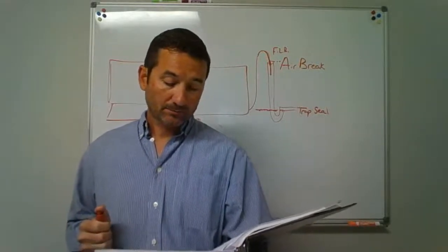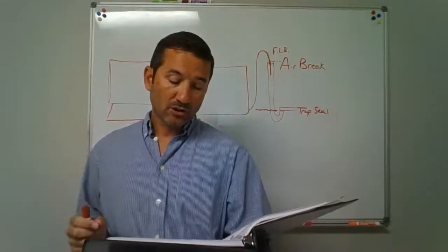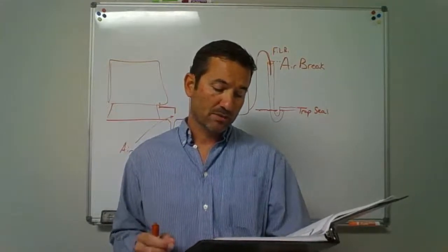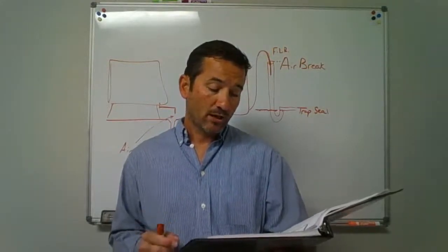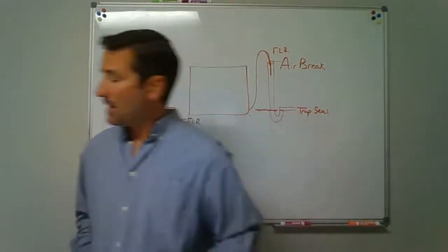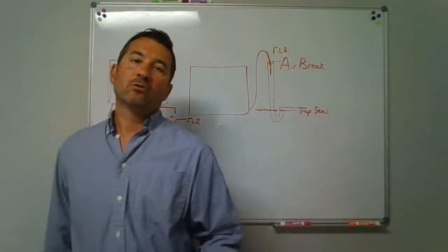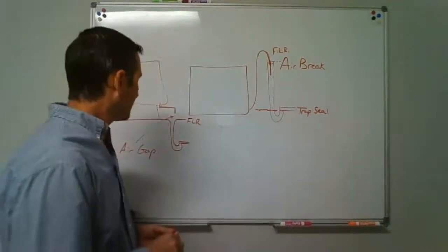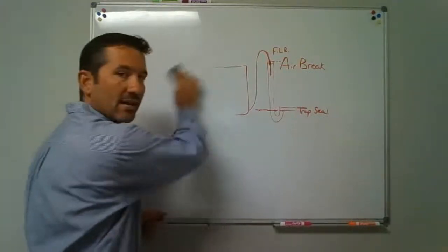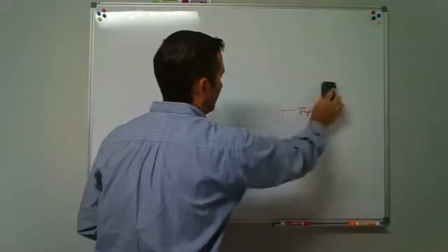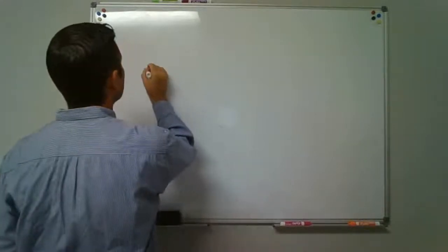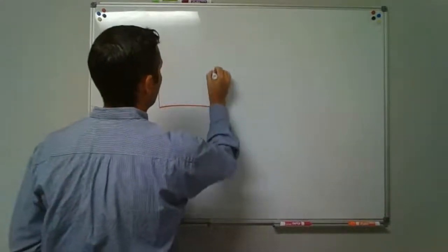Okay, food handling. Equipment and fixtures utilized for the storage, preparation, and handling of food shall discharge through an indirect waste pipe by means of an air gap. Each well of a multiple compartment sink shall discharge independently to a waste receptor. And that might be a little different, if you work at a restaurant, check that out. Multiple compartments. So you got the large stainless steel sinks, and often you'll see those as big three large sinks here, okay?